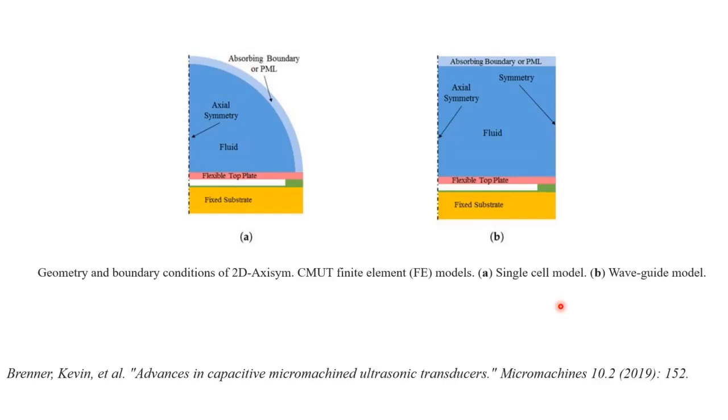In this brief presentation, I'll talk about how you can simulate a CMUT or an array of CMUTs in COMSOL using an axisymmetric model. By axisymmetric, it means you don't have to model the entire 2D geometry. The symmetry is assumed in all the domains, for example, pressure acoustics, solid mechanics, electrostatics, whichever you use. So COMSOL knows that the part of the model being simulated is symmetric. You don't have to include the entire geometry.